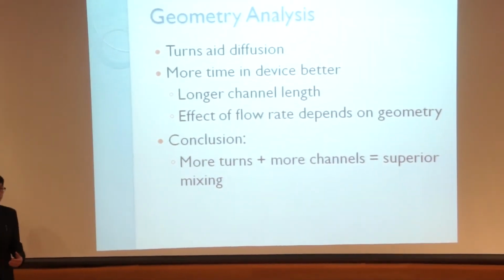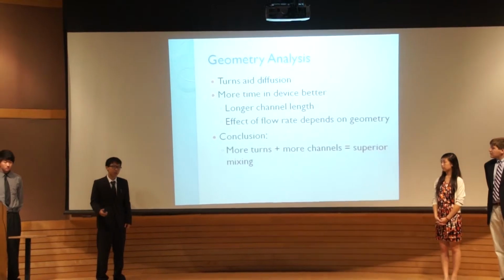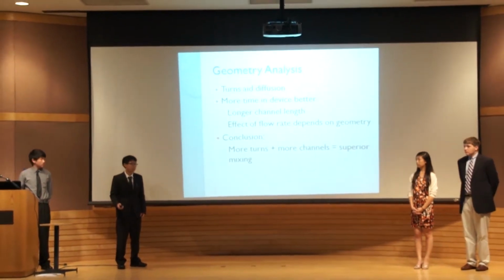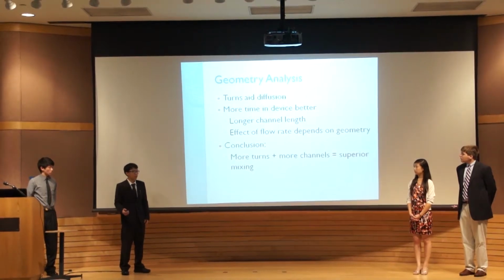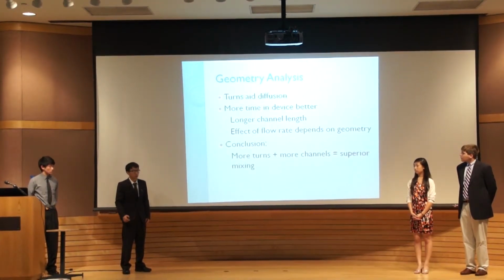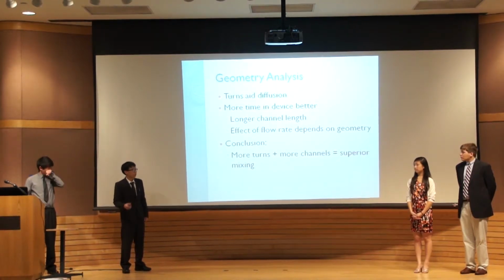We found that turns aid in diffusion. Turns allow for greater dispersion of the fluid molecules and change the momentum, which decreases the resistance to mixing. We also found that more time in the device is better. Something that directly correlates to this is a longer channel length. The longer channel length, like device 2, which had a channel length of 57 centimeters, reached a very low mixing